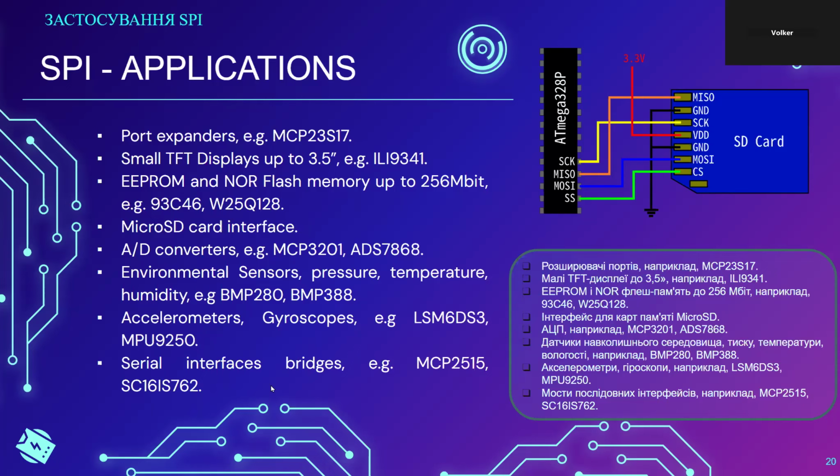I, however, do not recommend this because environments for embedded systems tend to be rough. SD cards, and especially the SD card holders, are not really meant for a rough environment. If it's part of an engine assembly, if there might be vibrations, I wouldn't expect the file system on an SD card in an embedded system to not become corrupted. What you could do with an SD card is, for example, store configuration data.